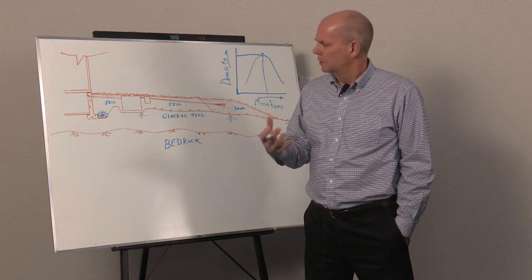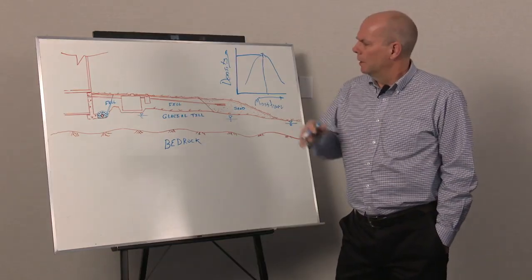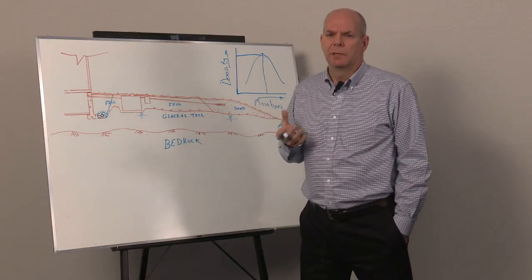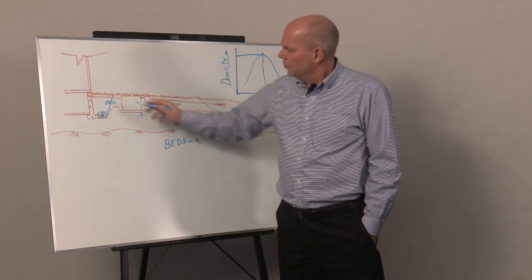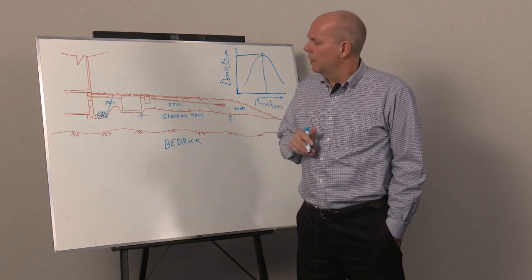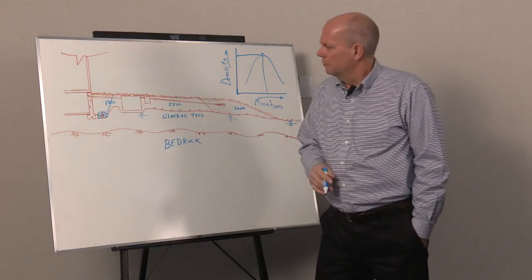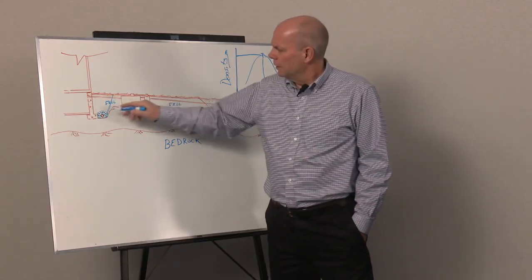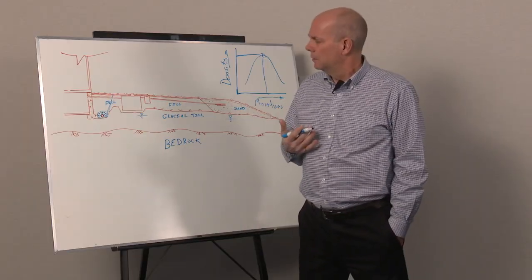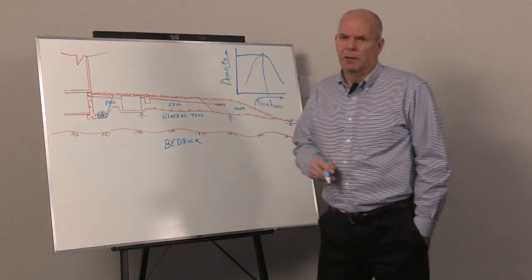It'll go in big lumps, clods. So that zone in the backfill is highly susceptible to long-term settlement from addition of water, surface water, wetting these lumps of material, softening them, and you get collapse. So if you go in, dig a shallow trench, put your pipe in it with a little bit of bedding and walk away from it, you run the risk of having this material continuing to settle and causing problems with your pipe. If you've done the backfilling yourself and you know that this material has been well placed, it's good, competent, compacted soil, then you're probably all right. But you have to assume that that's not very good material when you first get started.